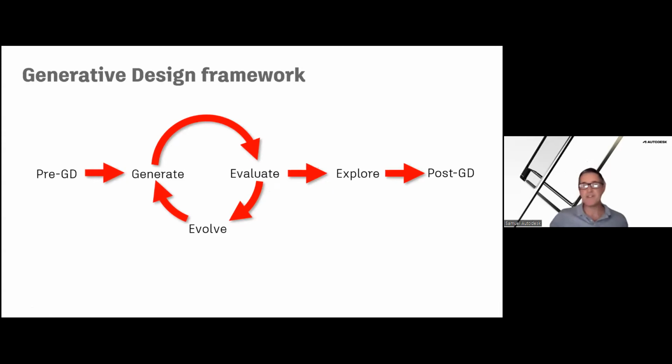So this is an overview of the generative design framework. Now, you want to be able to use these scripts that are set up to work for the different type of outcome-driven design that you're aiming for. So whether it be solar analysis or furniture layout or facade design, you would always work with this pre-generative design script. You would load that into your Revit environment.